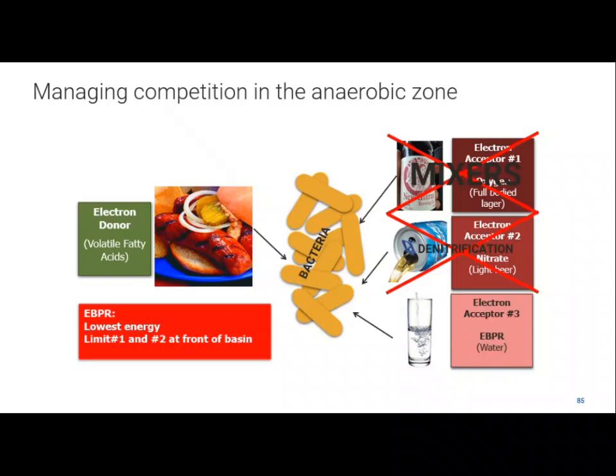All right, well, the next important part then is to make sure you denitrify. Like when we had the blankets up there before, if you're denitrifying in your blanket and get a little nitrate there, you're helping to eliminate that kind of temptation for the bacteria, and they just go after the PAOs. But otherwise, you have to have something in your process configuration to get rid of the nitrate in the RAS before it comes back to the head of the basin.